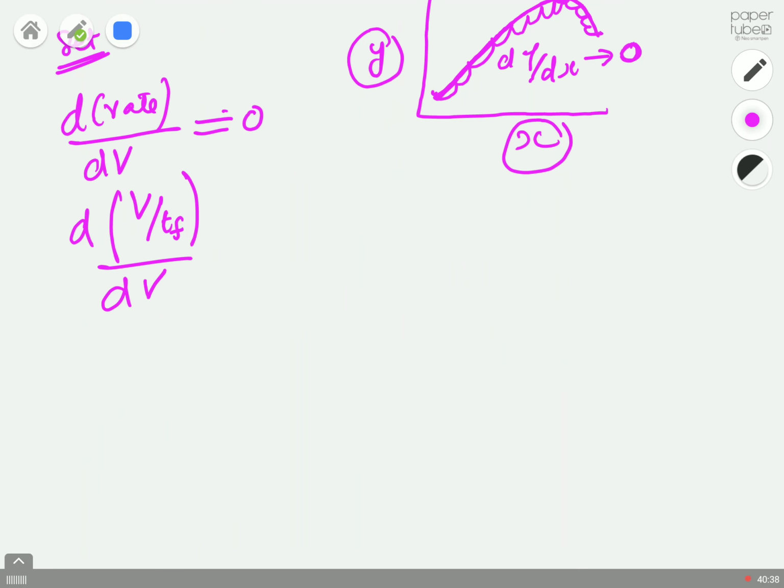with respect to the change in volume, the change in rate with respect to change in volume. If we set this value equal to 0, that should allow you to calculate the total filtration time for the condition when we are performing the filtration whose filtration rate is set to maximum.